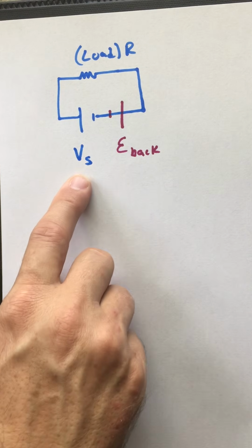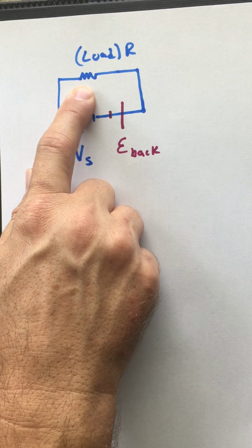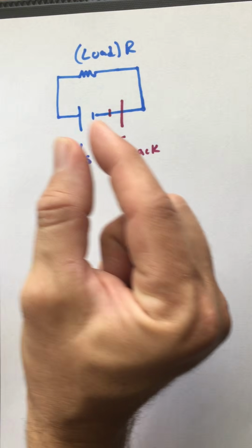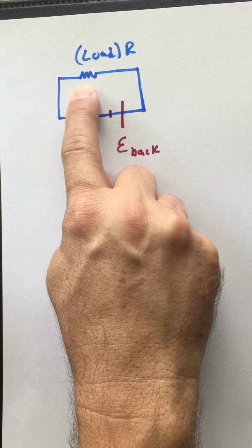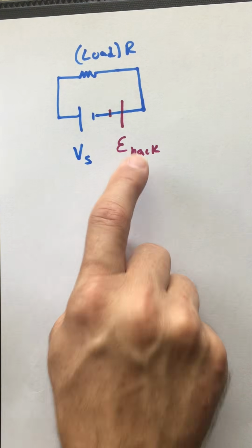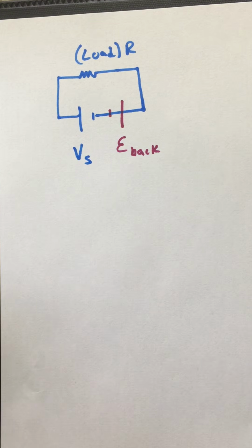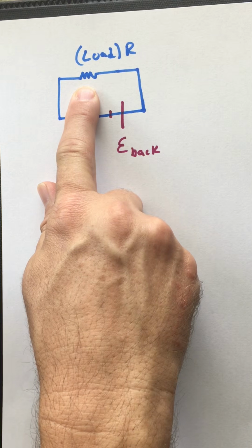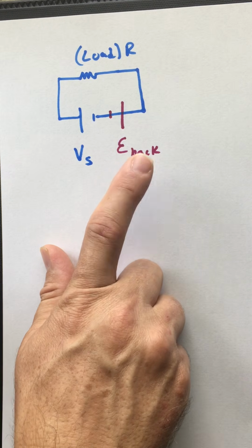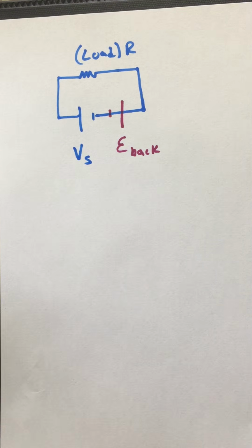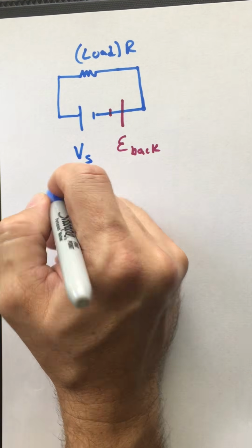And so when I close the circuit and this source voltage is presented to the load, and the load starts to rotate, then I get a really, really small induced EMF, small because the angular velocity of this thing is small. But as this thing ramps up to speed, this opposing voltage that's induced in the coil gets bigger and bigger until I'm at some maximum speed, my final omega, and then I've got the full back EMF. So the source voltage here is a constant, assuming that I have good wiring in my house or good batteries.